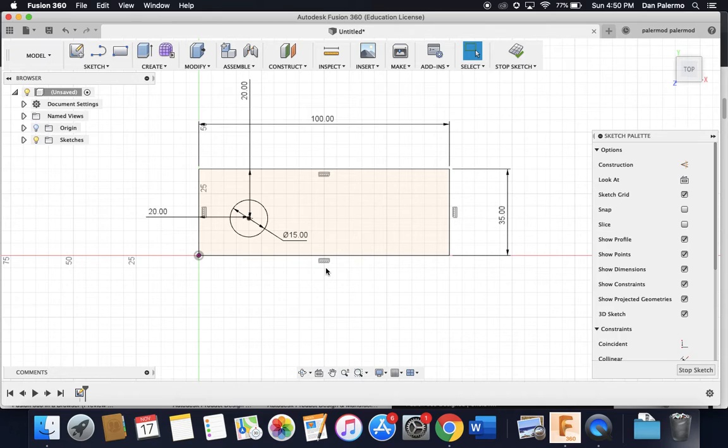All right, so I'm going to create what's called a construction line. And that brings me to one of the tools on this right-hand side here, which are so important, the sketch palette. I can create construction lines a lot like the tape measure tool in SketchUp. I can just create temporary hidden lines that aren't part of my actual entity, but I use as reference points.